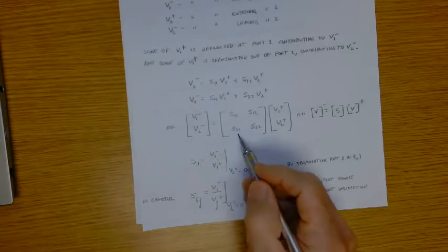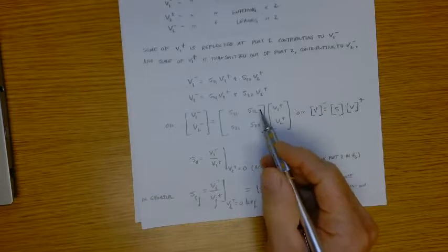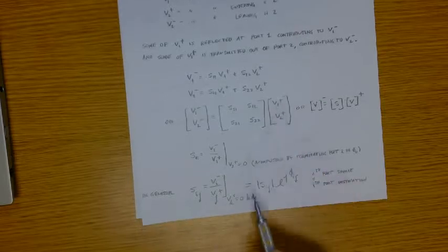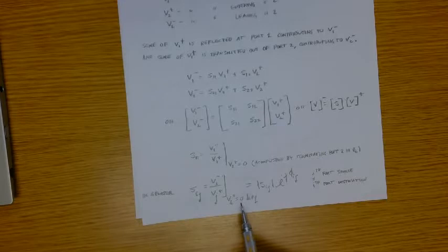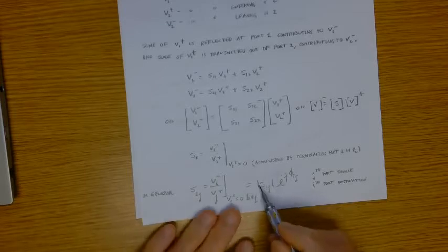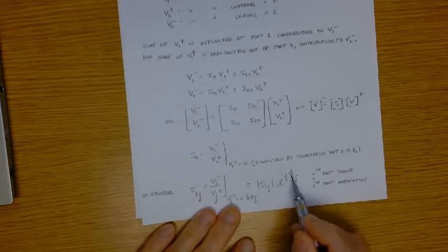So we'll want to compute S21 and S12 as well. And in so doing, in order to set these other incident voltages from the other ports to 0, you're going to have to terminate those ports. Again, that's how you achieve this. And in general, the scattering matrix elements are complex numbers, right? Some amplitude and phase.